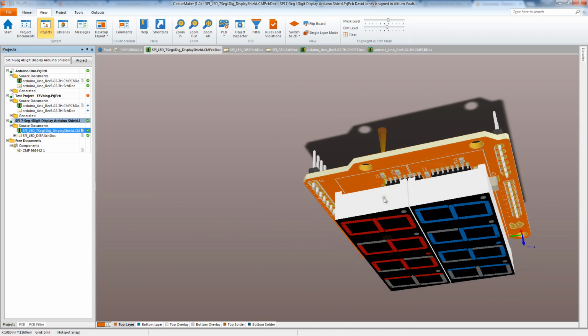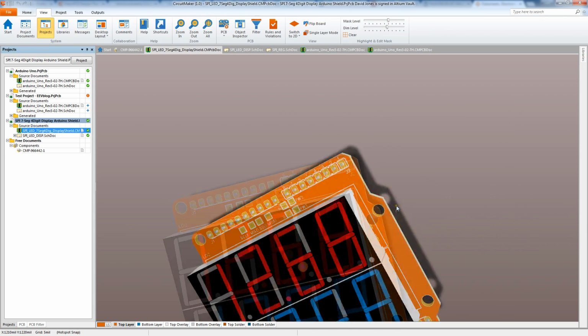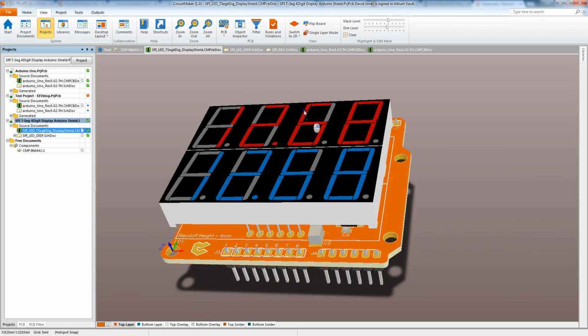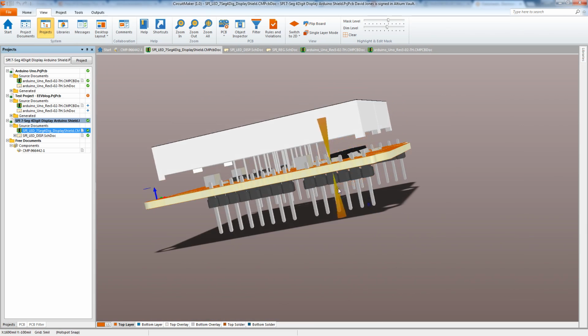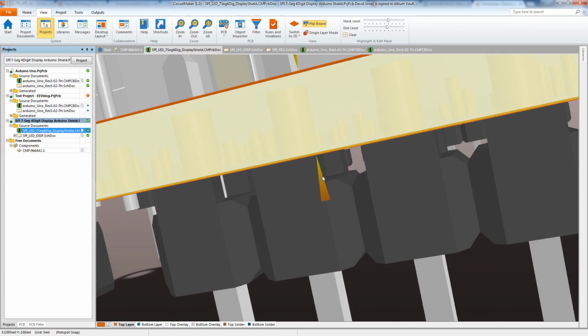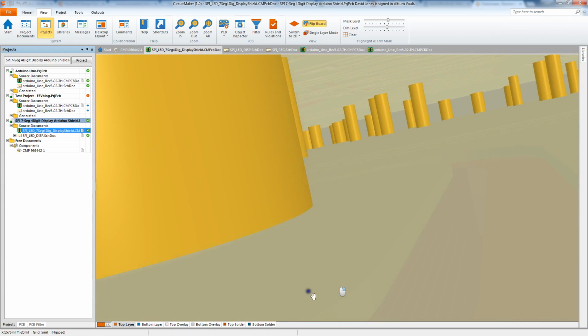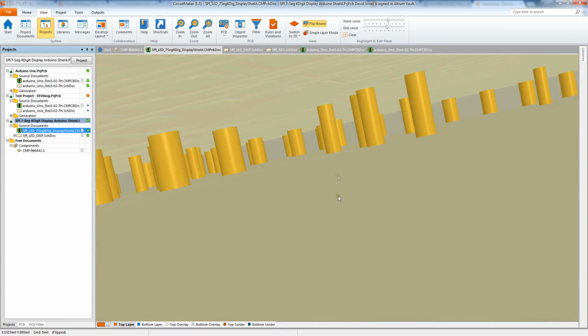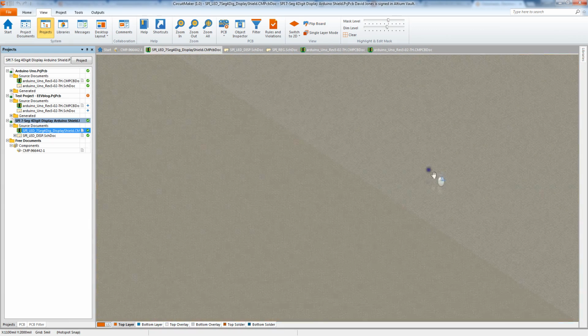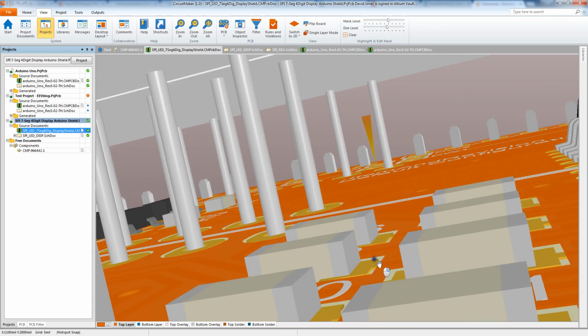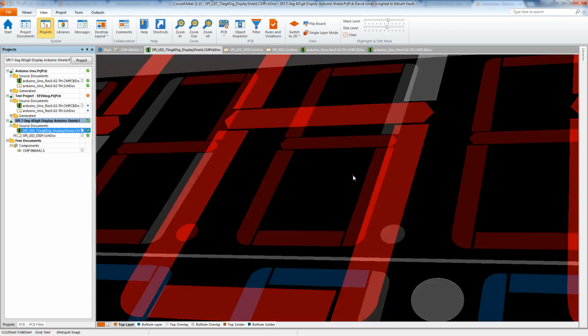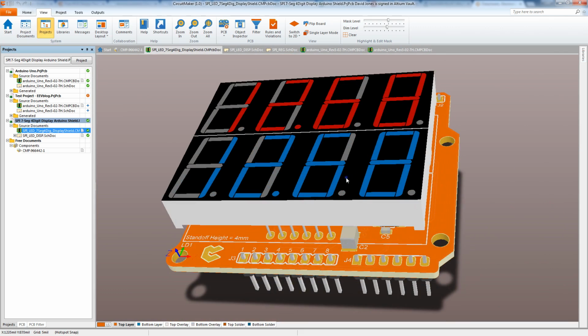A couple of the keys, like the 0 key and things like that, still work from Altium Designer. And we can do stuff like fly inside the board. Sorry, I'm doing this with my mouse. I don't have my space navigator that I was used to when I was working at Altium, but we can fly inside the board, under the part and things like that. So, fantastic. Just hit the 2 or 3 key.